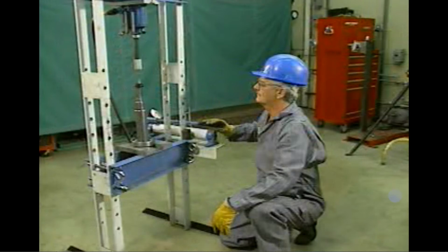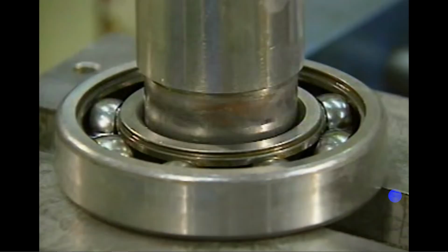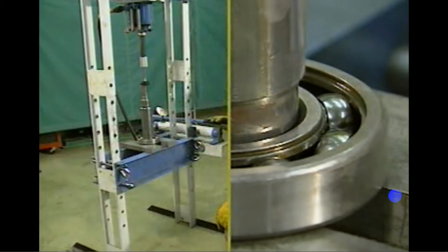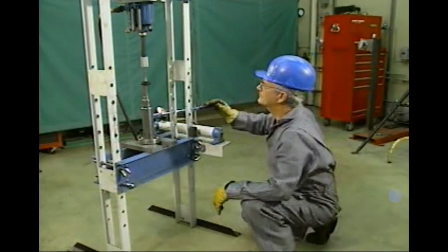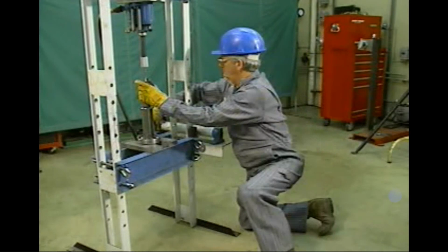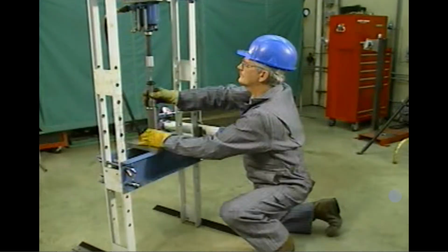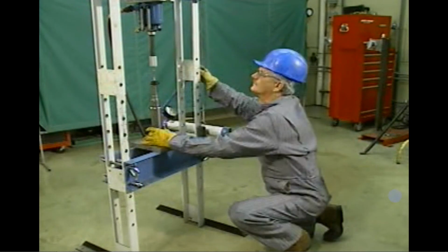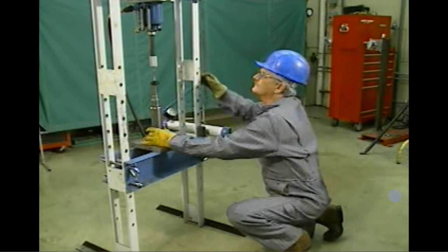He watches the shaft carefully to make sure that it moves smoothly into the bearing. If the shaft does not move smoothly into the bearing, the mechanic must stop the press because the bearing might be jammed. If this happens, the mechanic must correct the problem and then recheck the alignment of the bearing, the shaft, and the ram. He can then restart the press.